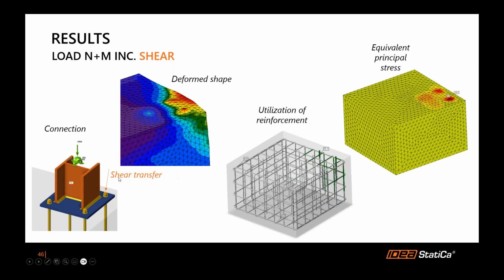And finally, here I have an explanation. I have a similar use case as demonstrated by Andrzej in Connection. And I have set that for the shear transfer, I will only use this highlighted anchor and the anchor that we cannot see. And in this anchorage close to the edge, with the shear force acting in the direction outside of the block.